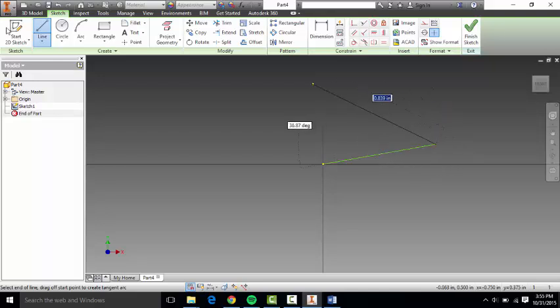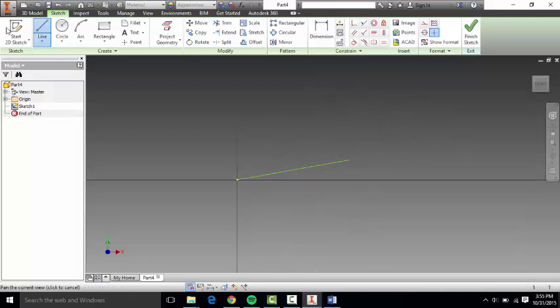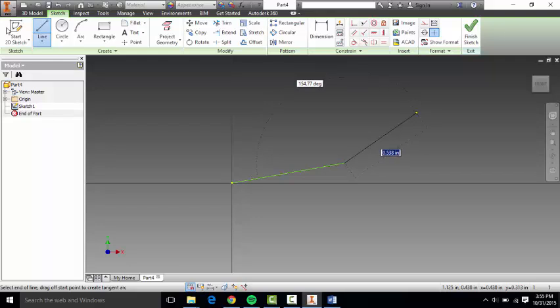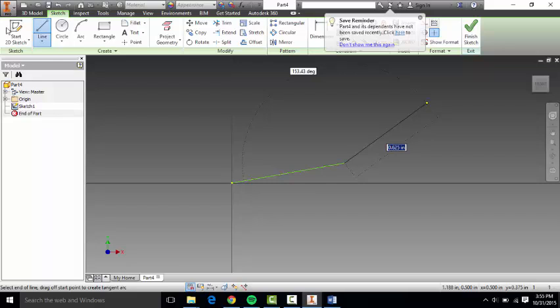Okay, and I still have the line tool up. It doesn't go away right away. But this time I do care how long my line is. Let's just say I did. And you can see that, again, I can type in exactly what I'd like. This time it's not the coordinates of the endpoint, rather it's the length of the line and the angle that it makes.